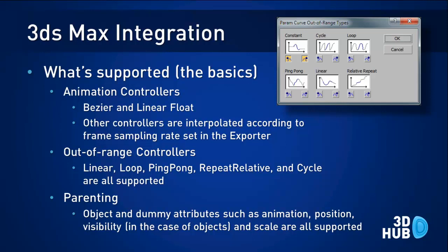Another facet of the export facility is parenting. We do support object and dummy attributes such as animation and position, visibility. Just so you know, we can't apply a visibility to a dummy, so you do have to use objects when parenting for visibility reasons.